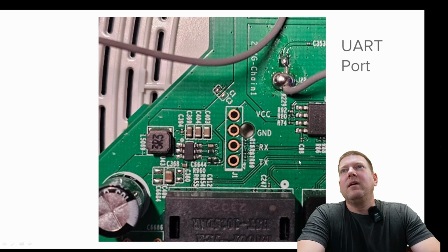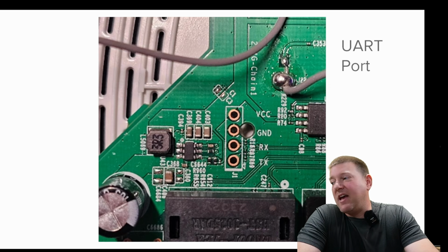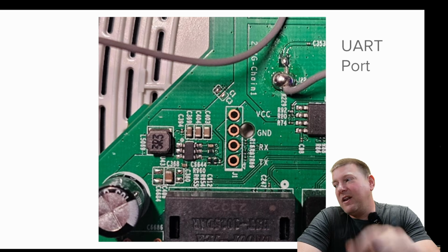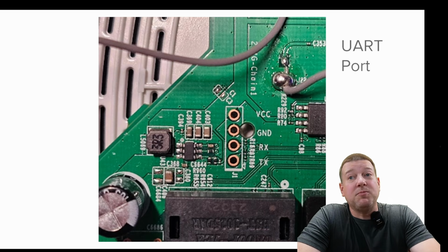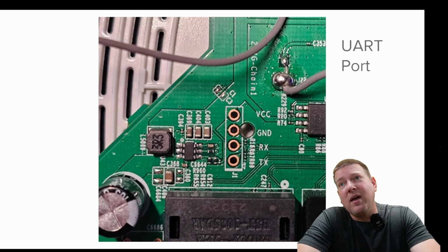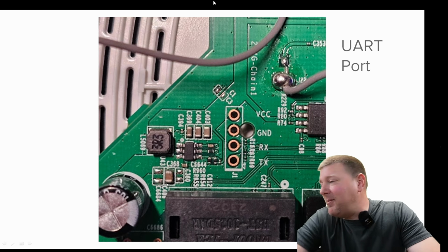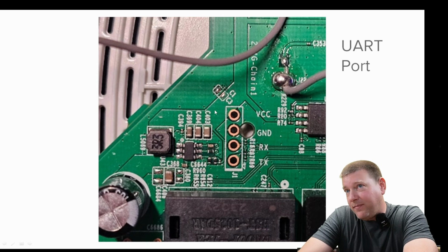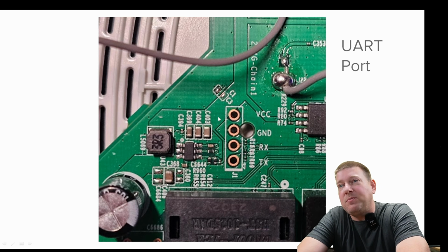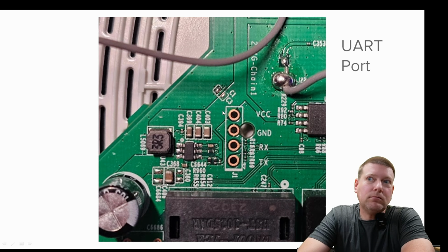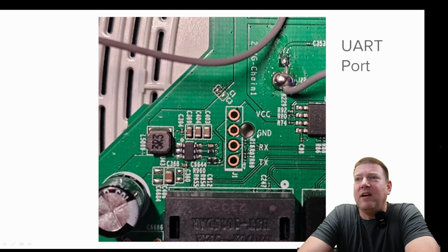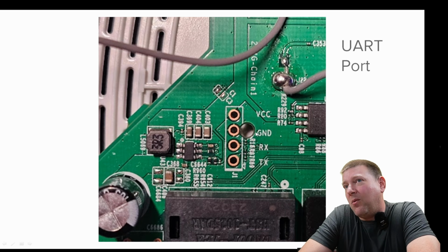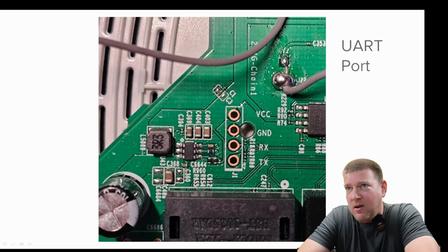All right, so that's UART, and here is that little UART jack I just pointed out to you over here on the Respironics board, and it looks just like that, okay? Now this one is a little bit different than what I've seen on many of them. Normally, the edge pin, either this pin or this pin, is ground. Luckily, it's labeled here. And you can kind of figure out what's ground and what's not on this one.